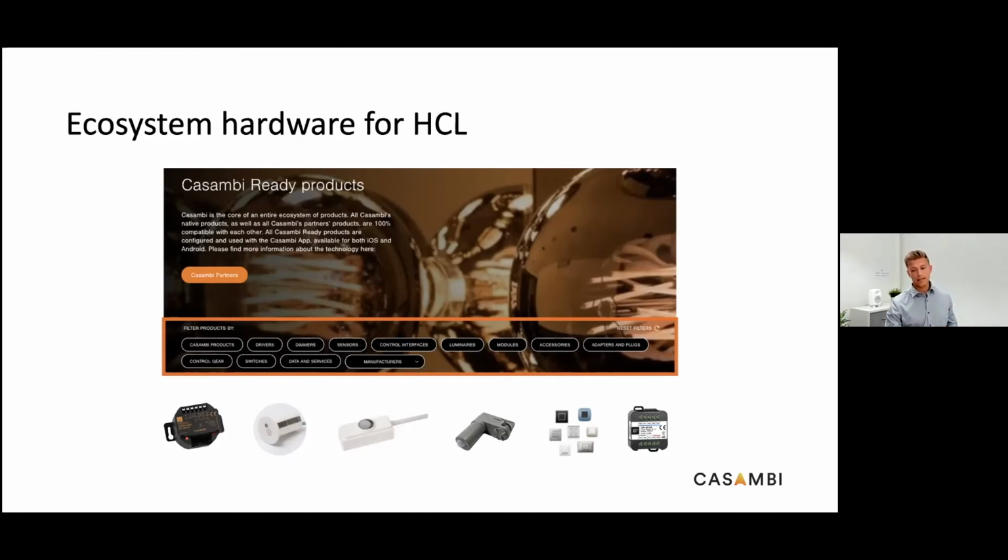I've also put in the bottom right different types of switch components, because human-centric lighting is all about how the users and occupants interact with the lighting system. One option is a fully autonomous system. You could have just a daylight sensor in the project, ensuring you maintain X amount of lux according to the daylight that's coming into the room. Alternatively, you may find that the occupants would like that customization, that flexibility to control the lights above their desk, for example. Then they can use the Casambi application, or you can have switches placed wherever you like across the room from multiple different manufacturers. You could have batteryless switches, battery powered or mains powered, and you've got the full ecosystem available to choose from, which is on our website.